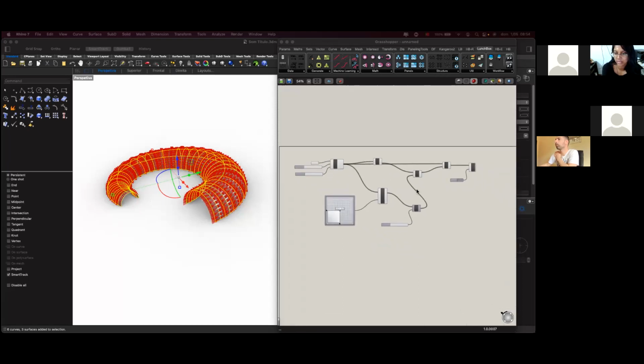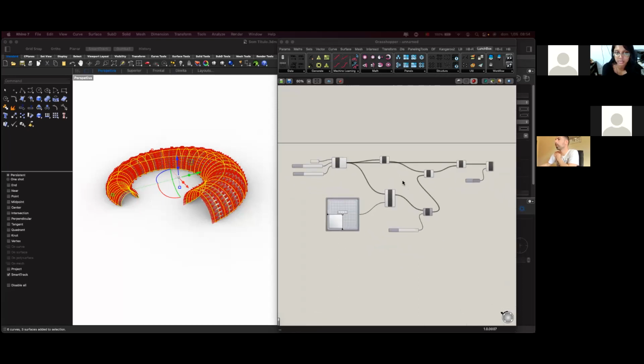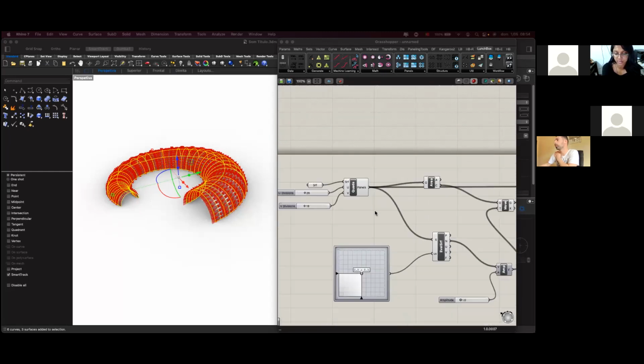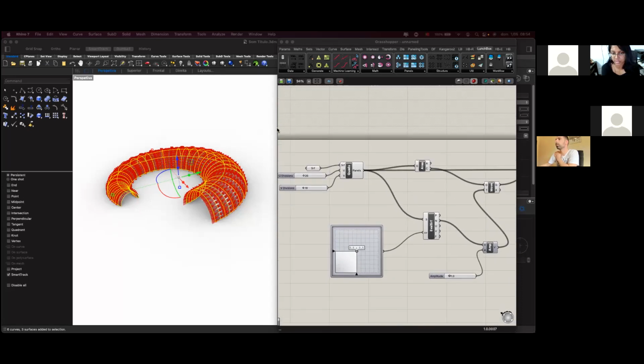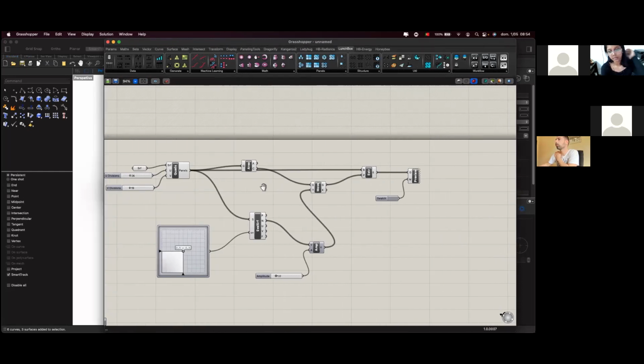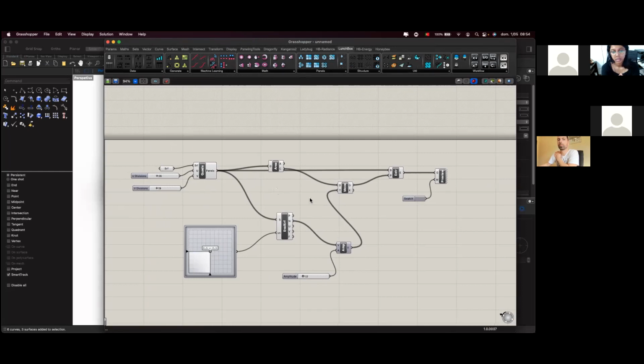I don't know what I did wrong. Can you just show me your Grasshopper algorithm? Sure. Maximize it so I can see the entire set of components used. I don't mind if I don't see Rhino, that's fine. Just the Grasshopper preview is enough. Your algorithm looks perfect. There's nothing wrong with it. Just that you have the preview of all the components involved in the algorithm on. So select all of the components and hide the preview. Just the final preview alone, let it be on. It's just the final one.